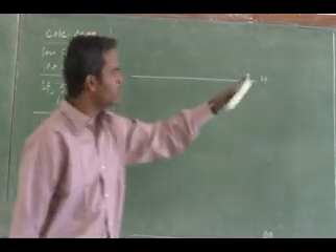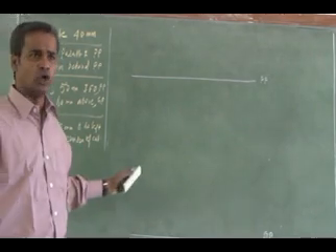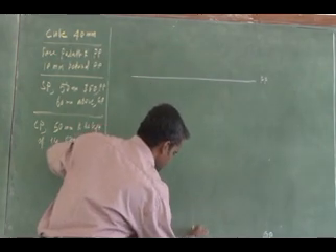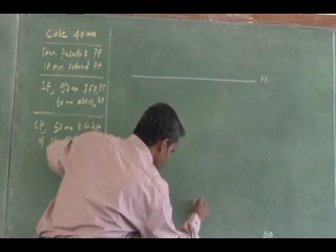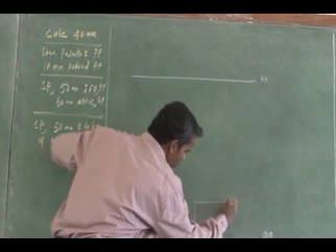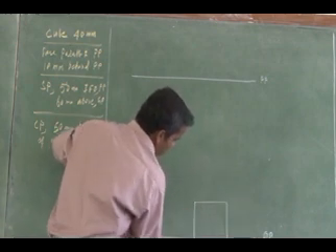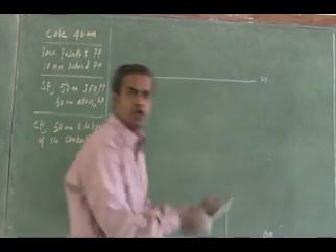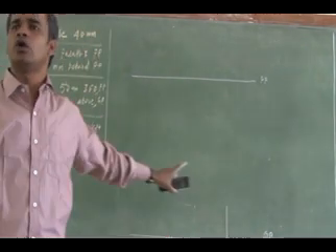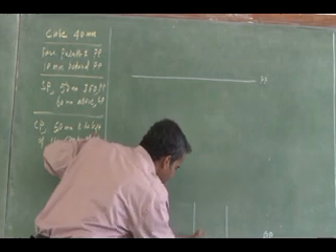Right. Then immediately you draw the top view and front view of the object given. It's a cube. So the cube front view will be a square. Everything you draw with an H pencil. In your drawing, only the perspective view alone should be darkened, right? Draw it with an H pencil, don't darken anything.